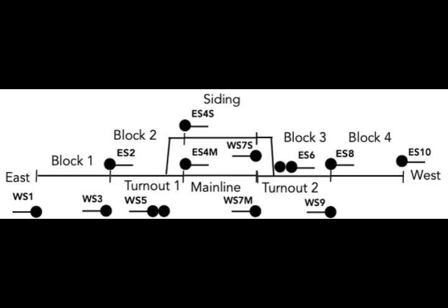Each turnout nano controls a 4-channel relay, in which channel 1 controls frog polarity, channel 3 switches previous block communications between the mainline and siding nanos, channel 4 does the same for the next block communications. Each turnout nano also has direct links to the mainline and siding nanos to communicate switch orientations to assist in determining if the nano has a previous and a next nano. A wire from pin 10 on the nano is connected to the nano's ground to simulate that a block is occupied.